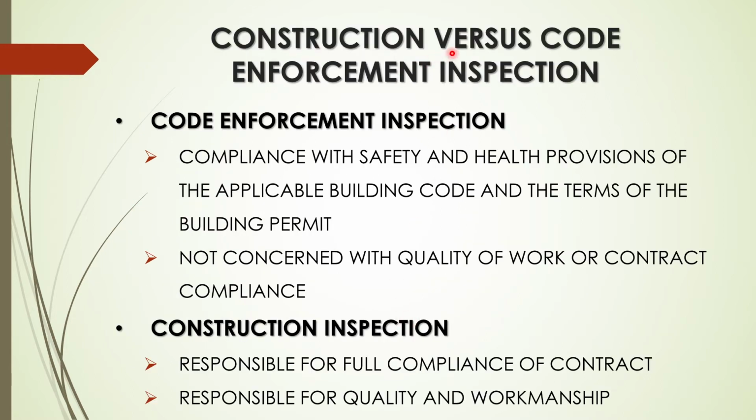Okay, construction versus code enforcement inspection. I just wanted to determine the difference. You can do both, but this is the difference. Code enforcement inspection: compliance with safety and health provisions of the applicable building code and the terms of the building permit. Not concerned with quality of work or contract compliance. Basically, they show up at certain parts of the construction, they look at it, they leave, they sign off on